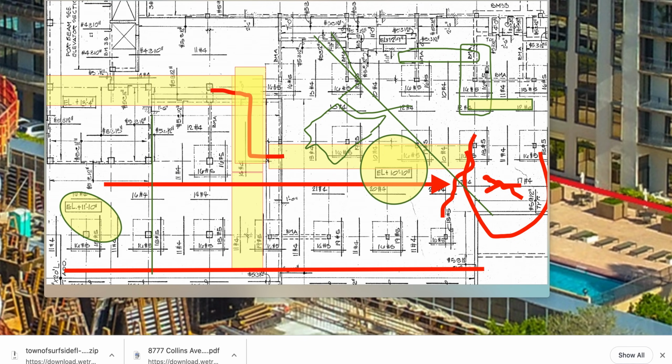So this acts as a beam also, because the spans on this now, they're funky though. This beam here is pretty big, even if it's a beam. I don't know how she was going to be built, but she was going to have something to her, because that's a heck of a span to go from here to the top of this beam, and then from this beam over to this wall. They were going to intercept it and load it, because it was too great of a span. The beam would be so high they would lose their clearance for vehicles to get underneath.